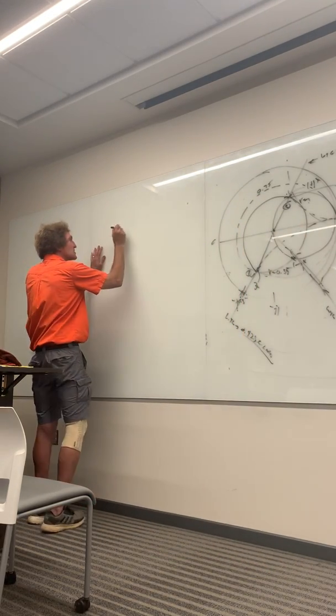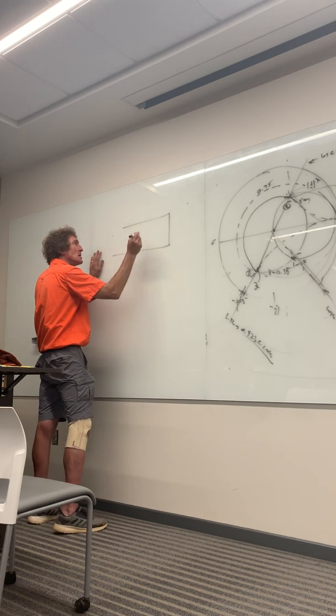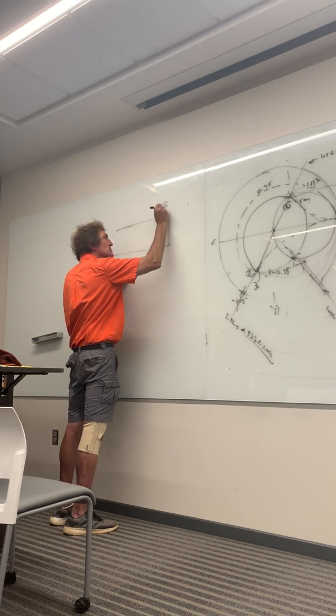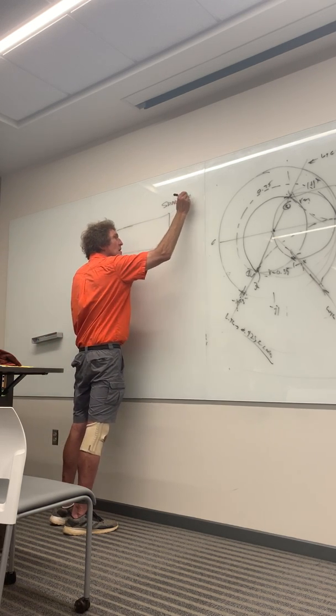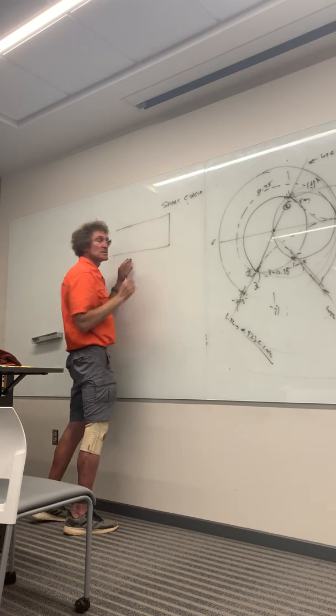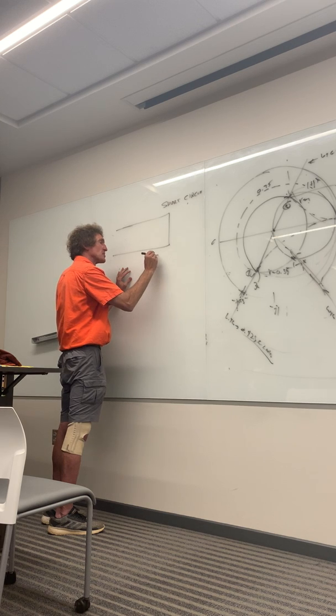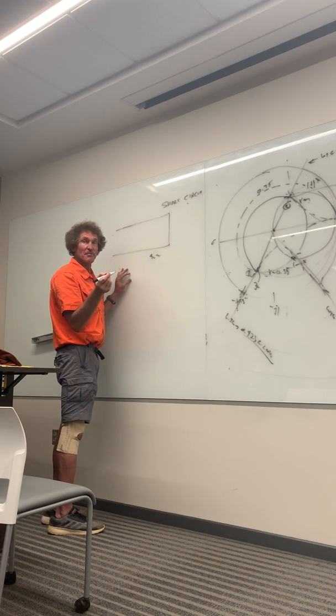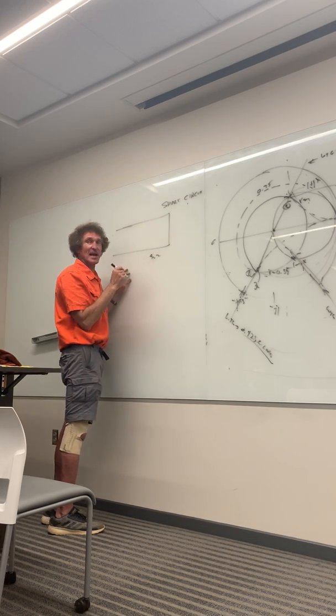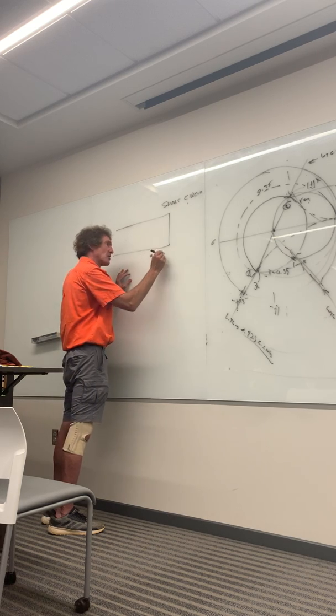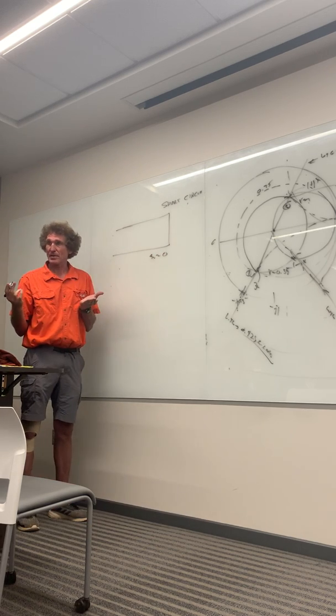Well, I start with a short circuit. So this is going to be with a short circuit. Now listen, I start with a short circuit, right? What is ZL for a short circuit, anyone? What is the value of ZL, the actual impedance? It's 0, right? So the normalized value is 0, correct?